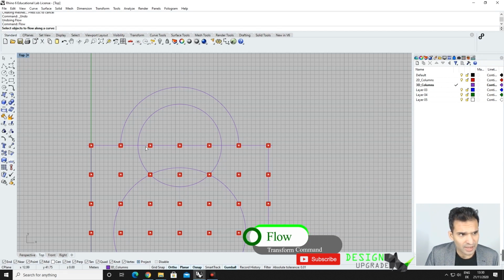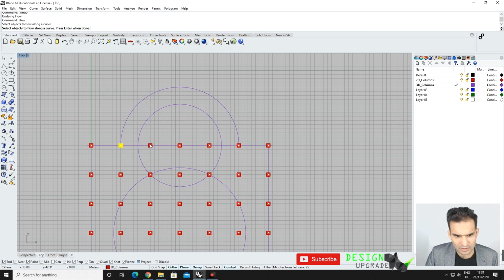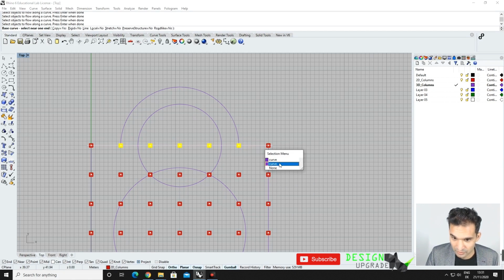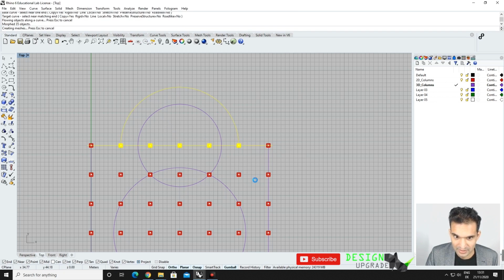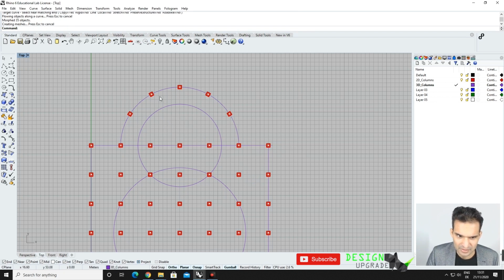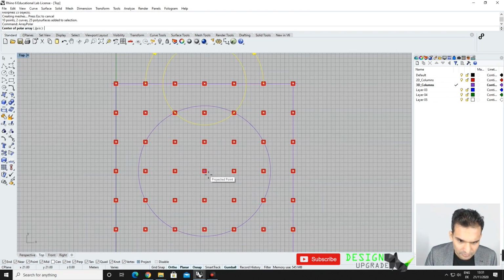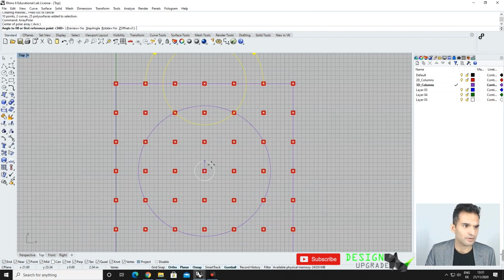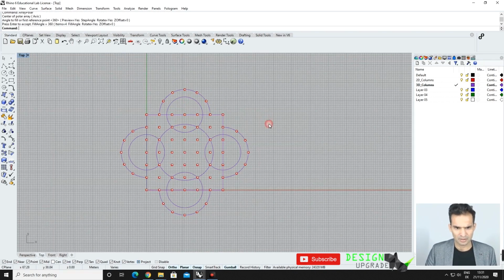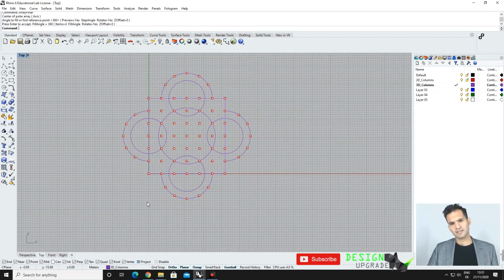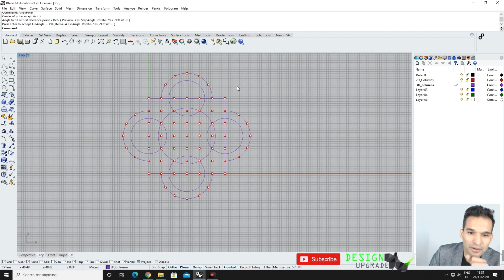Flow. And I want to now take those 5, these guys. I want to flow them on my new curve that I just drew and following this guy. And now we should have 5 pieces. These guys kind of align, which is nice. And with this setup, all of this good stuff, I now again do an array polar. Bring my center point, 4 items, enter, enter. Voila, this already looks better than my previous design, I guess. And now we are pretty good to go.